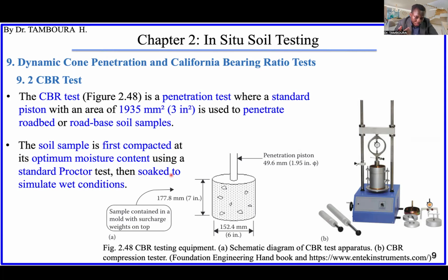Then it is not finished. You have to soak the sample to simulate wet condition. Put the soil sample in water so that you can simulate wet condition.